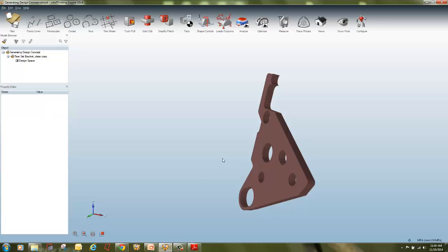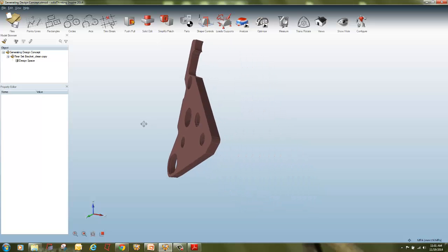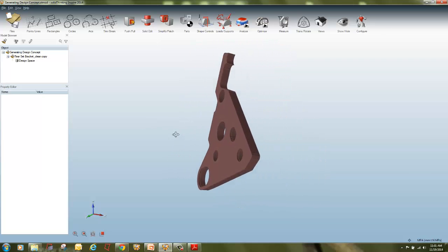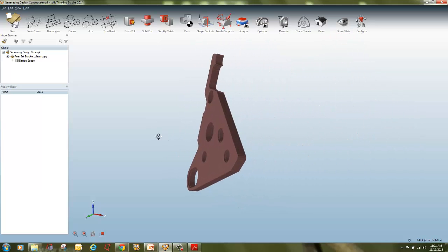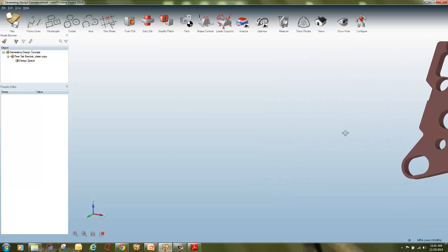The most convenient way to interactively pan, zoom and rotate the camera view is by using the mouse buttons. For finer control of rotation, use the view rotor in the lower left corner of the modeling view. To pan the view using the mouse, hold down the left and right mouse buttons and drag the mouse to pan the view. So once you press both the right and left mouse buttons, you can pan the model in this way.